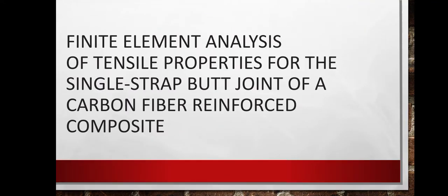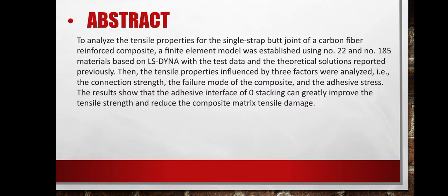Finite element analysis of tensile property for the single strap butt joint of a carbon fiber reinforced composite. The abstract. To analyze the tensile property for the single strap butt joint of a carbon fiber reinforced composite, a finite element model was established using number 22 and number 185 material based on LS-DYNA